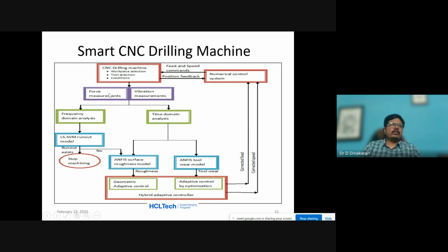How the force is progressing, continuously we are monitoring. At the same time, if it is not cut and the force is applied, what will happen? It will be converted into vibration or thermal energy. Say I have applied the force, because the tool is blunt, the component is only partially cut. Then what will happen to the remaining energy? That will be converted into some other form of energy.